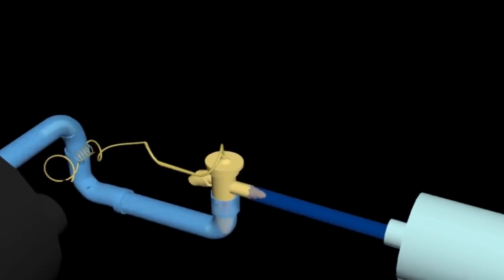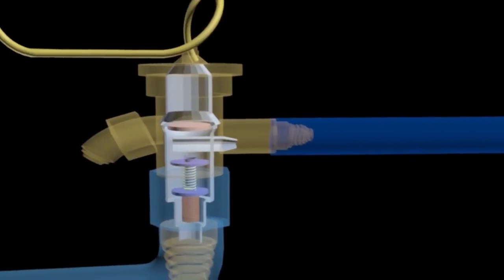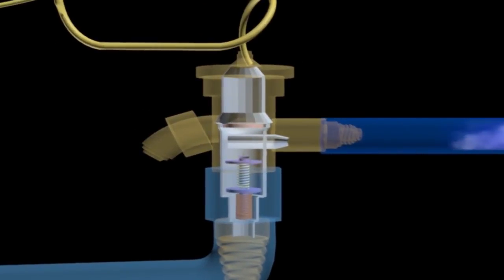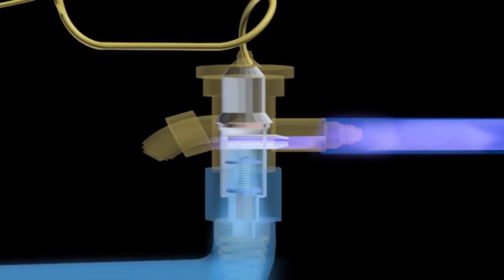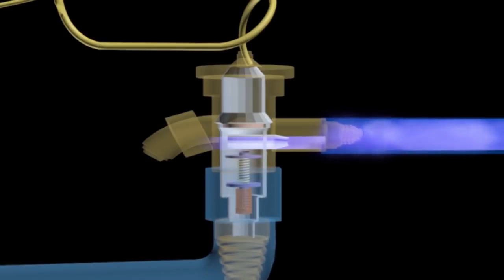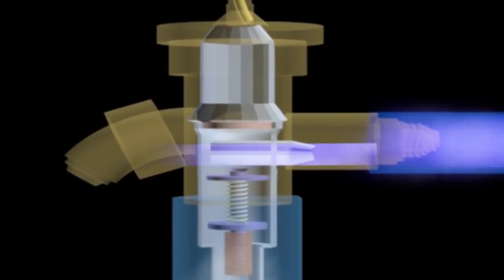Expansion valve. The expansion valve serves to reduce the pressure and control the flow of refrigerant going into the evaporator. When the pressure of the refrigerant has declined drastically, the temperature will drop dramatically, to lower than the chilled water temperature. In a centralized system, a TXV thermal expansion valve type of expansion device is used.